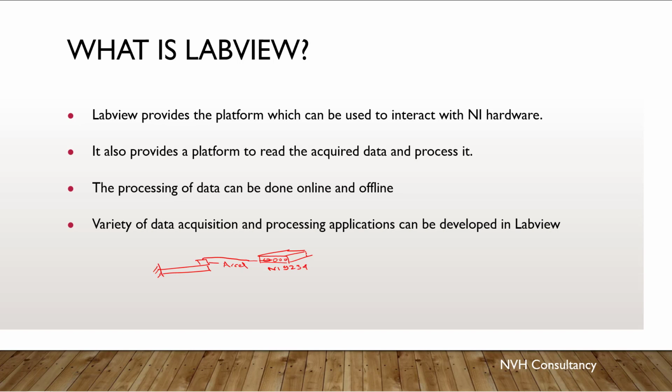Okay. Now this NI9234 is then connected via USB to your laptop or to your PC that you are using. Okay, so let's see. Suppose this is your laptop, and you will be connecting the NI9234 to your laptop, and over here you will be opening up your LabVIEW program basically. So all the data that you have collected for this cantilever beam, you can see over here via various block diagrams and functions that are available in LabVIEW.